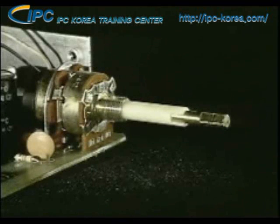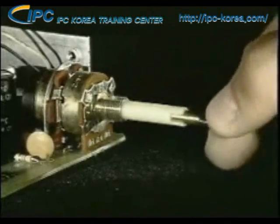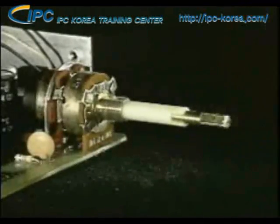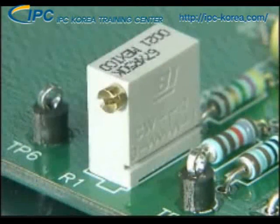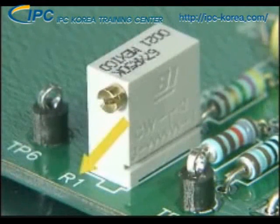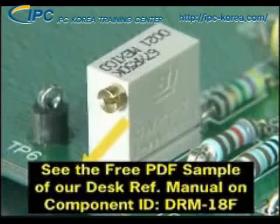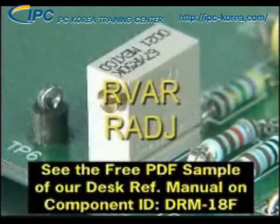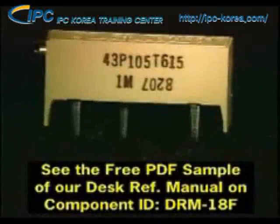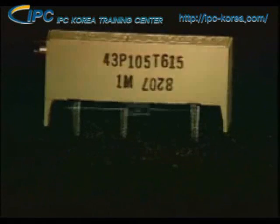can be changed or adjusted, either by turning a shaft or sliding a contact. The maximum value is usually molded into the component body. Along with the letter R, the reference designator for variable resistors may be VAR or ADJ. Variable resistors typically have a non-symmetrical lead pattern that only allows them to be installed in one way.